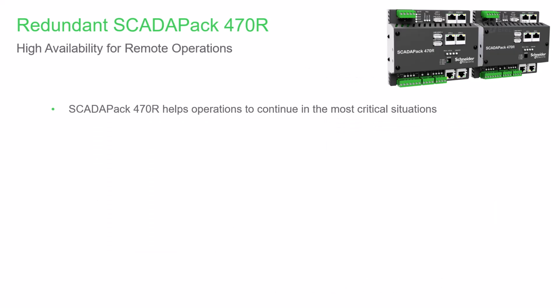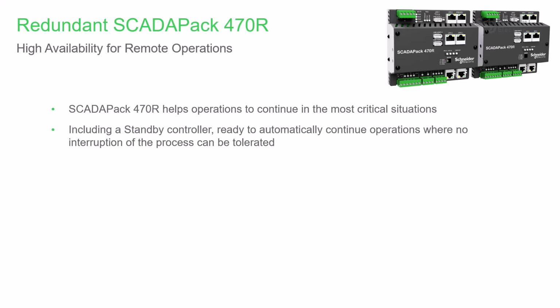The SCADAPack 470R provides high availability for remote operations. 470R helps operations to continue in the most critical situations by including a standby controller, which remains ready to automatically continue operations in situations where no interruption of the process can be tolerated. Control of key processes is maintained through the use of redundant IEC logic.